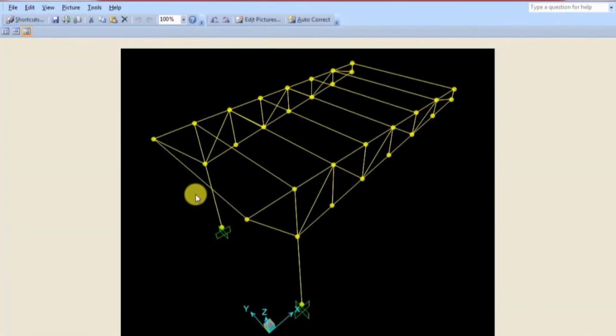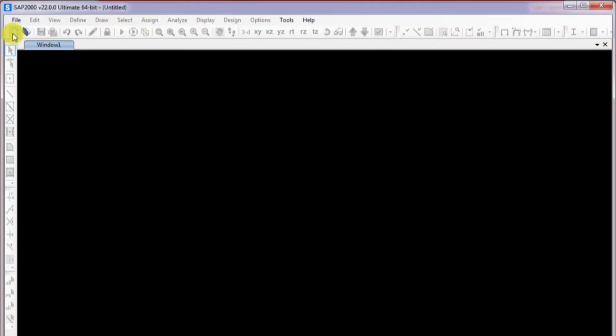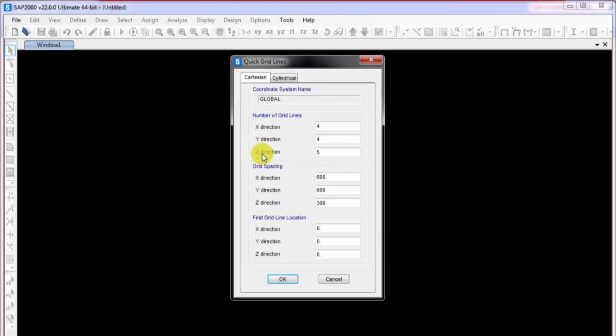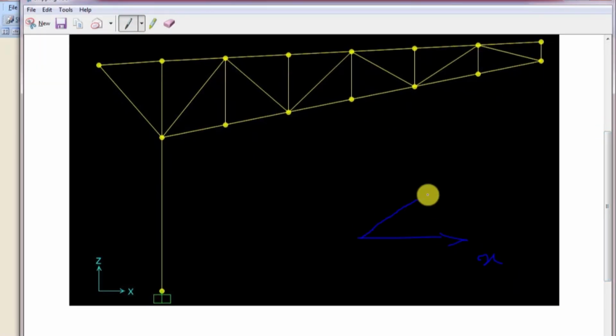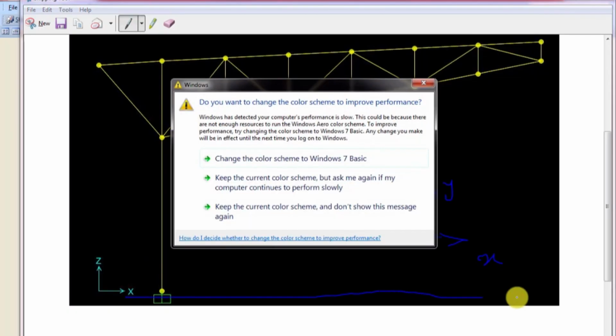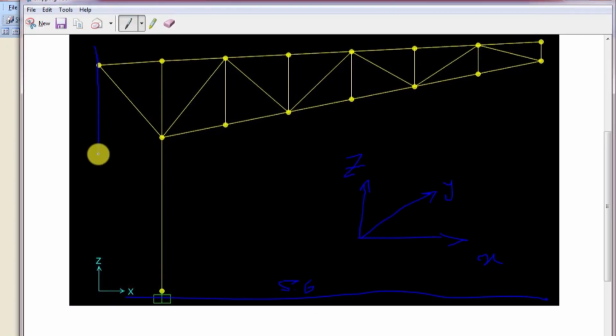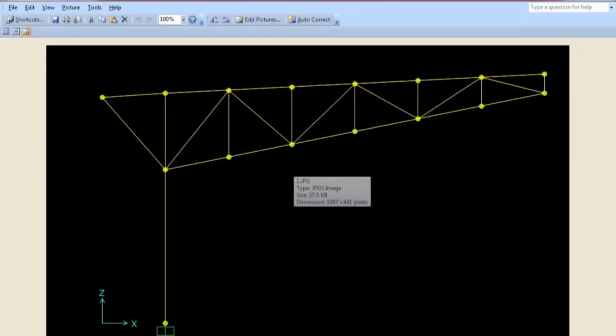In this tutorial, we are going to design and analyze a steel truss parking canopy for a single vehicle using SAP. First, let's define the structural concept. We will model a truss system similar to the configuration shown here, which is commonly used for lightweight parking shelters. For a typical car parking space, dimensions of 2.5 by 5 meters are usually sufficient. However, in this example, we consider a slightly larger layout for better clearance and constructability.